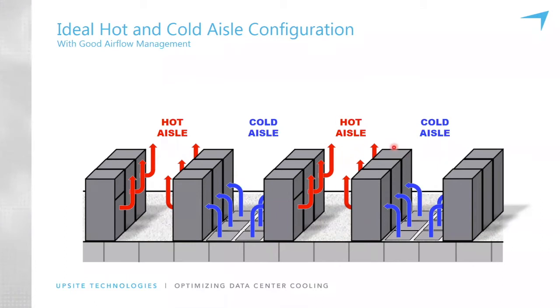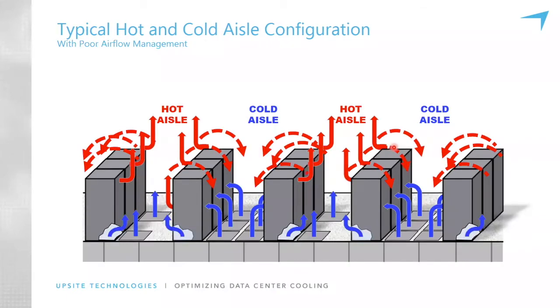However, airflow management is invisible. Air moves and we can't see it. So unfortunately, this is the reality of what's going on in many computer rooms. And just a few things to point out: we have air coming out of unsealed cable openings underneath the cabinets. There's some misplaced perforated supply tiles in a hot aisle or maybe out in an open space in the room. And we've got exhaust air recirculation over the tops of the cabinets or maybe around the ends of the rows.